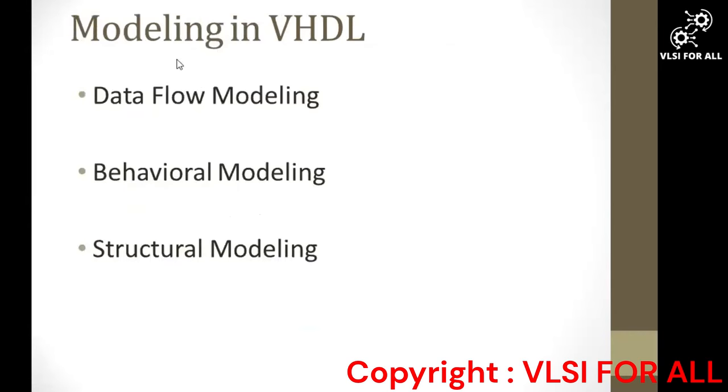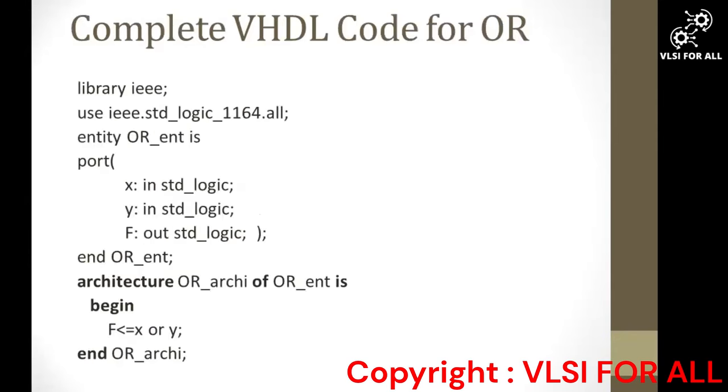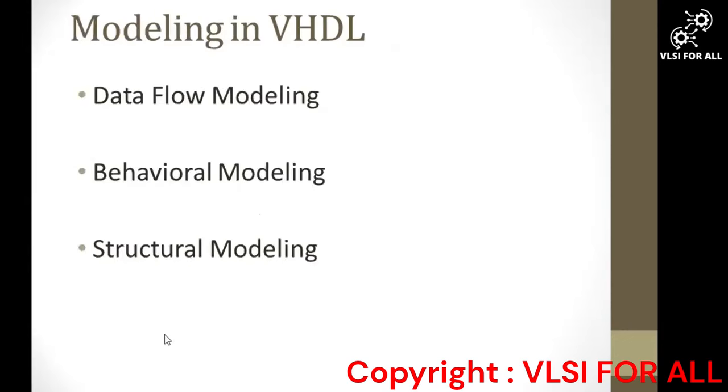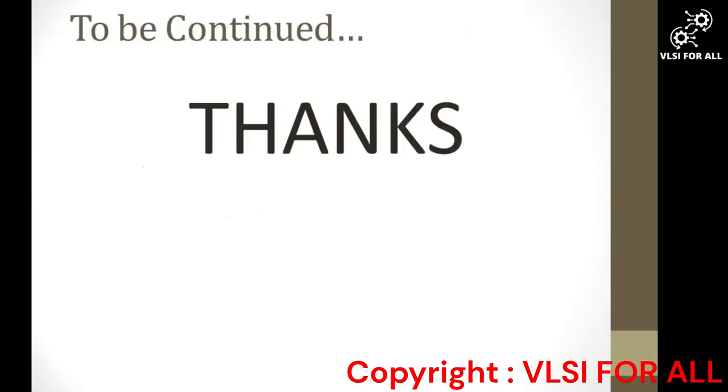After that, this is the modeling in VHDL. For writing this logic, F equals X or Y, we can use three different modeling styles. Here it is a behavioral modeling. We can use data flow modeling, behavioral modeling, and structural modeling, whatever we want. We will study all of these in detail. Thank you. It will be continued after that.